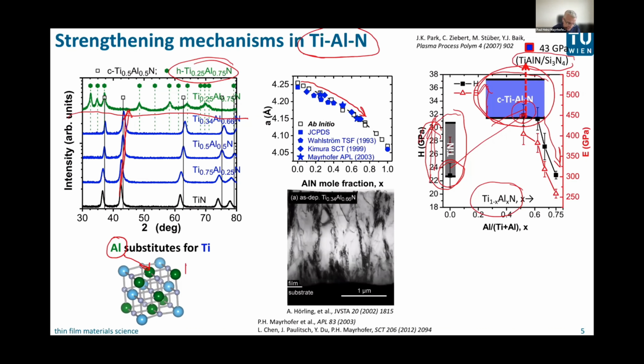Then they segregate out and form boundaries, silicon nitride, amorphous silicon nitride boundaries. Then actually what we do is we limit grain growth during the growth of the material. That ends up with small sized grains, and then we have even higher hardness. Beyond 40 gigapascal is often seen, right? So we have actually 3 of the possible 4 strengthening mechanisms available in this titanium aluminum nitride.